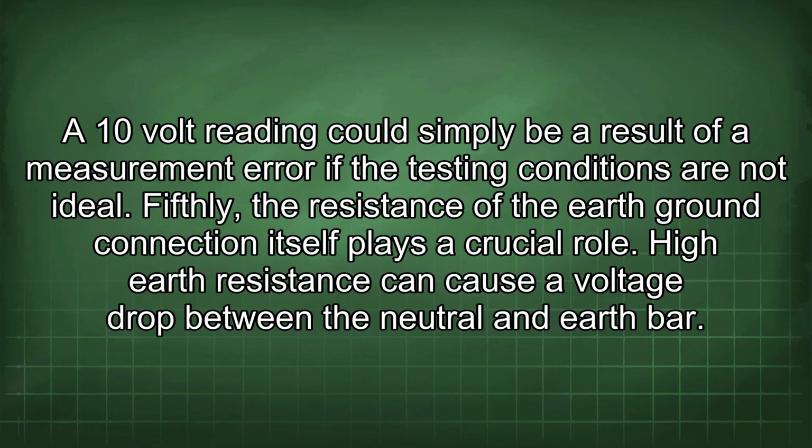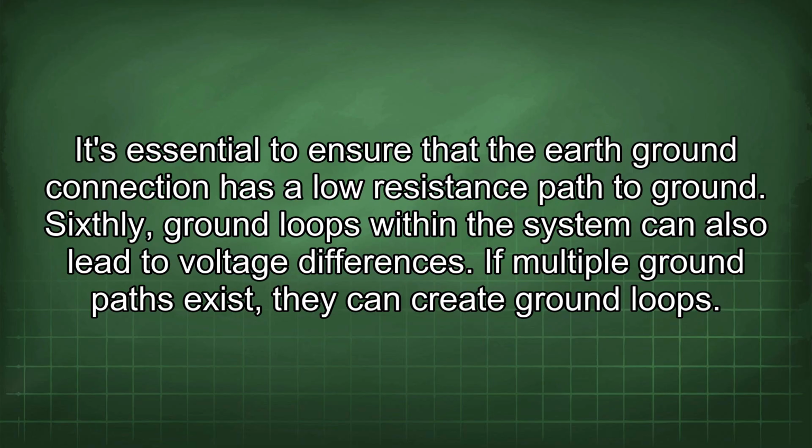Fifthly, the resistance of the earth-ground connection itself plays a crucial role. High earth resistance can cause a voltage drop between the neutral and earth bar. It's essential to ensure that the earth-ground connection has a low resistance path to ground.